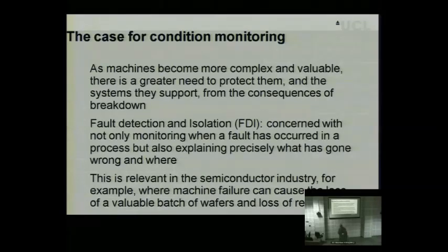It's about detecting change. So the fact that you might not have exactly the right parameters at the moment in terms of your model, but you're happy with your plant, then so long as your observer gives an output error of 0, and you look at what the nu equivalent is, and you say, well, this is good. This is my plant operating as I want it. The question is, has this changed? Because that might indicate that something has changed in the plant.